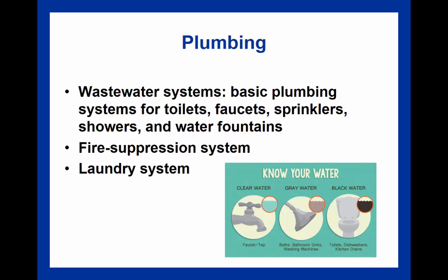So, fire prevention really focuses on different questions about whether or not a facility complies with all appropriate codes and industry standards, whether or not they have a fire suppression and alert system available, and if so, whether or not that's adequate, whether or not potential hazards that would not be usually put out by water are taken care of by other means, whether it's chemicals or powders that could be used to put out fires, sensitive information like computers, and then whether or not there are escape routes and exits available and outlined, and whether or not the employees are trained in terms of how to respond to fires.